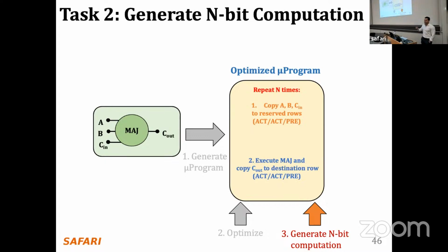And then in the end, if you have 32 bits, you're going to have to take 32 steps to get the output results that you want for the computation, for addition, for example. If it's a multiplication, it's worse, because bit-serial multiplication scales quadratically with the number of input bits. So if you have 32-bit multiplication, you're going to have 32 times 32 steps for the computation.